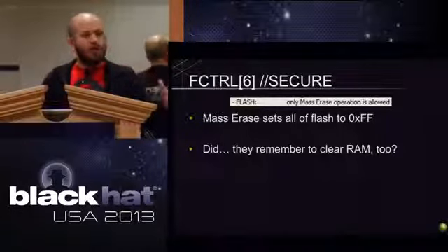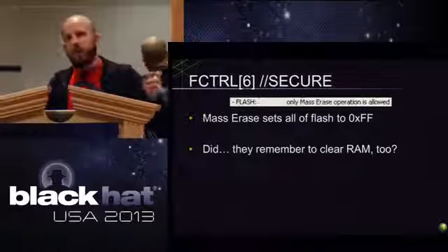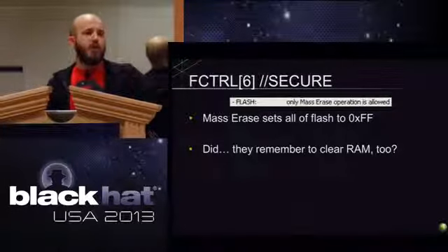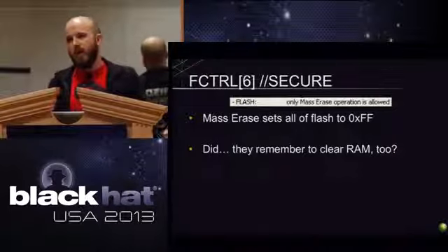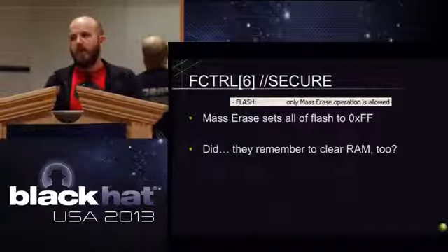So in the first 30 or 60 cycles, what's normally happening is that an instruction runs that sets this bit and says turn off the debugging interface. The pre-boot phase ends, and then the debugging interface does not come up. So how do you get back into that device, right? They didn't want that to be a bricked scenario.